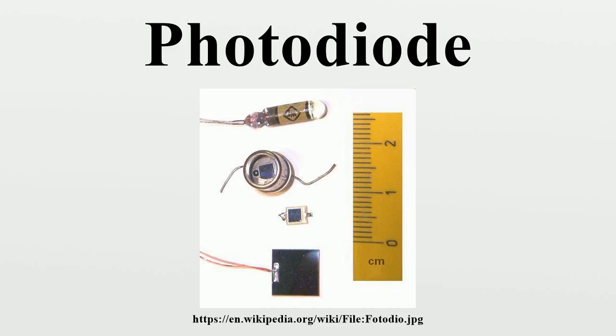Disadvantages compared to photomultipliers: small area, no internal gain, much lower overall sensitivity, photon counting only possible with specially designed, usually cooled photodiodes, with special electronic circuits. Response time for many designs is slower.